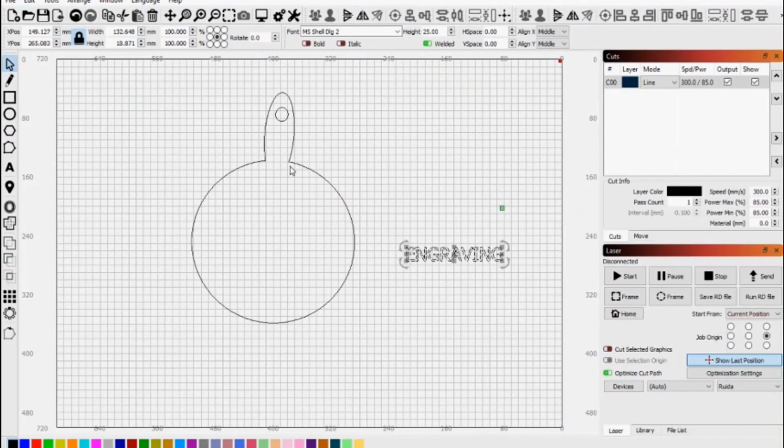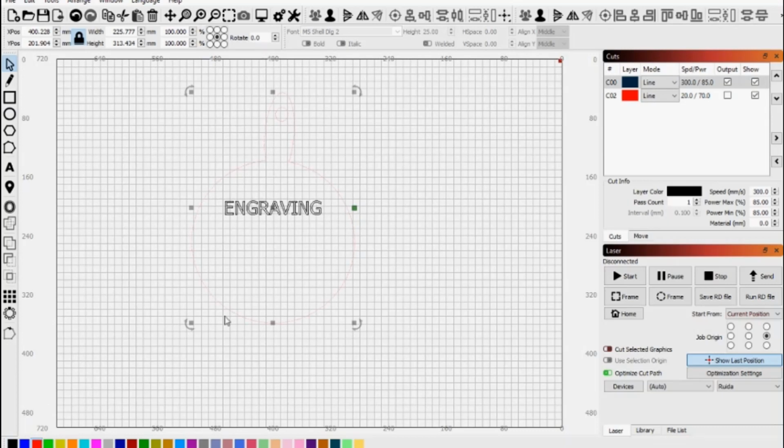So some things that I do a lot are chopping boards, so I just wanted to go through how I might add some engraving to this chopping board, and I wanted it dead center, for example. Now I've got an irregular shape, so if I ask for this to go dead center using the dead center option, it's not dead center on the circle of the board. So say I had this circle, let's just, for the sake of this demonstration, I'm going to make the chopping board, I'll show it for now, but so I've got the chopping board in red. What I could do is create a circle that is the same size as the one I'm using, and we'll make that one blue.